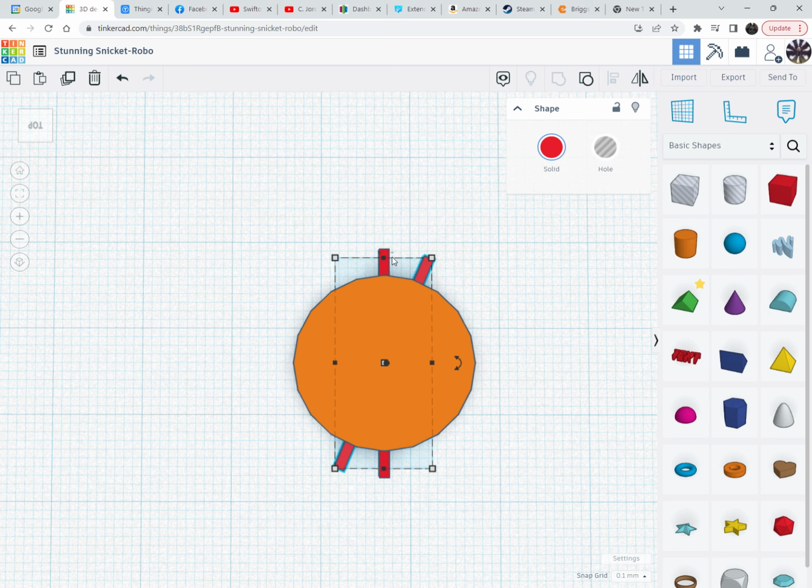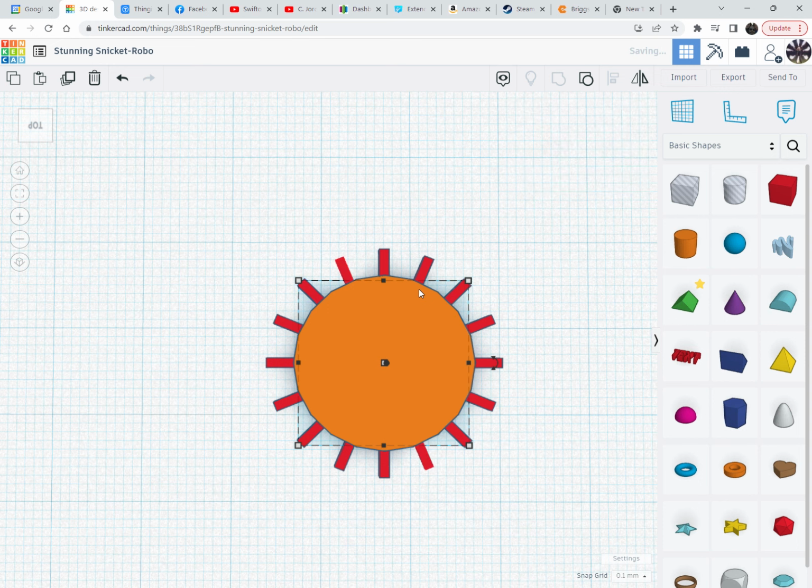So now I've duplicated the 12 and 6 o'clock and rotated them that first click. Now watch what happens if I hit duplicate again. Control D. There's the next one. Control D. There's the next one. Control D. And I can populate the hands of a clock just like that by using Control D. As long as I don't click off, because once you click off, Control D forgets what you did.